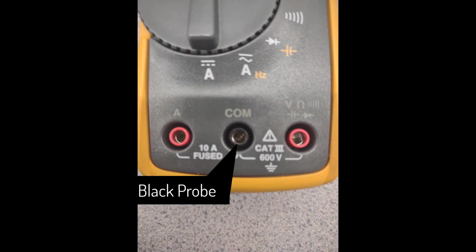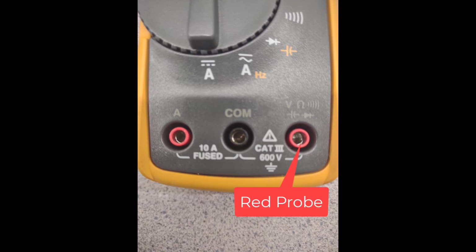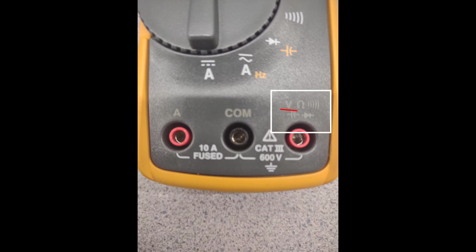And here, the black probe for the common, for the yellow one, and then the red probe over here. The reason why we're doing that is because we have that little V above it, right there, for voltage for that port.